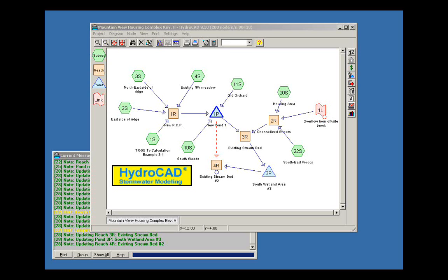The curve number method is used instead of other procedures, and it's designed to incorporate all of the different flow regimes. One of the interesting things about the curve number method is that it's using the length of the flow path, but the slope that it's using is the average over the entire subcatchment. So it's sensitive to changes in slope anywhere in the system, as opposed to just looking at the slope along the flow path and ignoring the slope of the rest of the subcatchment.